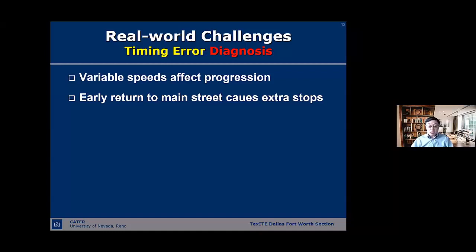If you are really experienced, you hold a time-space diagram, and you think, well, this might be an early return, but you are not sure. So you need to know if it's indeed an early return or something else, a transition, for example. Early return is normal. It doesn't mean anything is wrong, but you just need to know that.